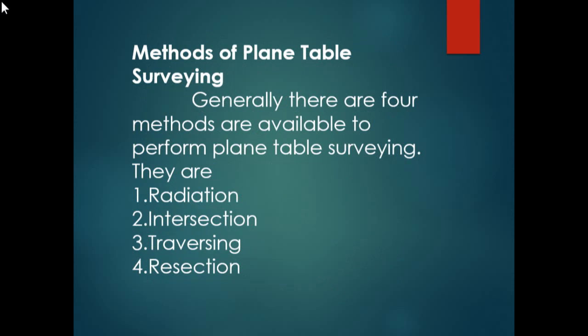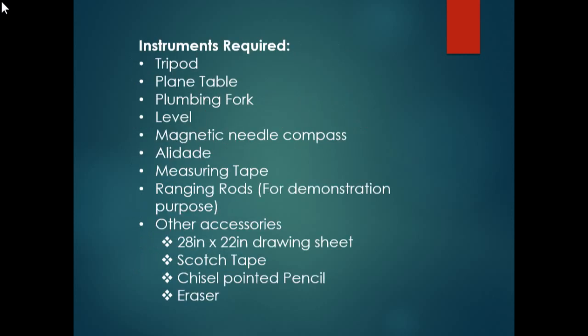There are four general methods available to perform plane table survey: radiation, intersection, traversing, and resection. Of these, we are going to study the radiation method today. That is the first and most important method.